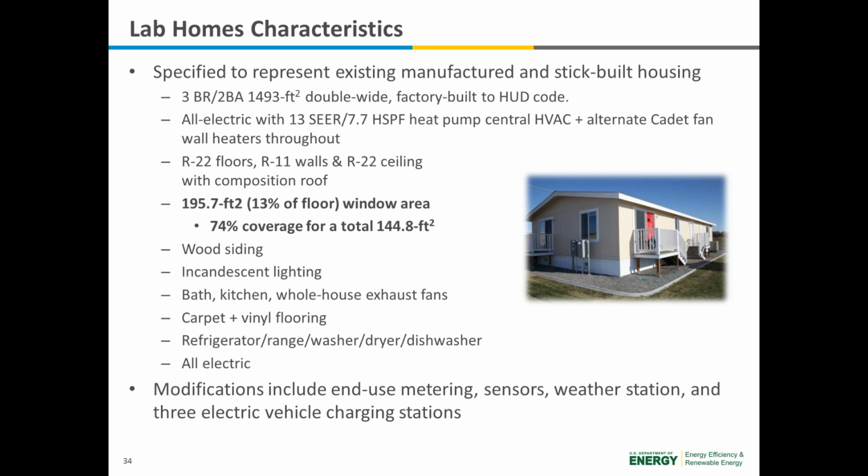We have R22 walls and R11 in the roof and in the ceiling. The window area we have is 195 square feet, or 13% of the floor area. This note here right below, and I'll talk about this a little bit more later, is that only 74% of the windows, or 144.8 square feet, were covered by our interior low-E storm windows. I'll talk more about that later, but basically that is because Quanta does not make an interior storm window large enough for these sliding glass doors.